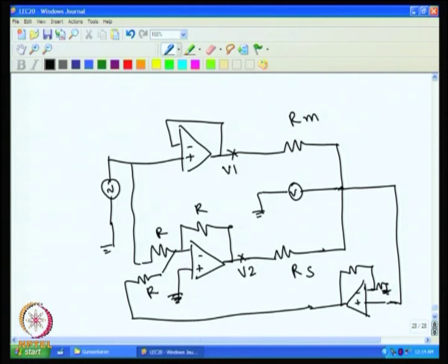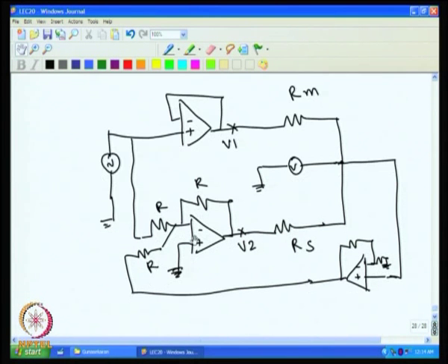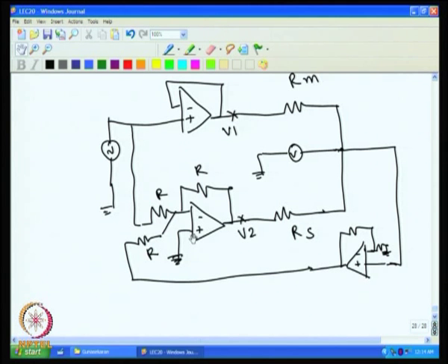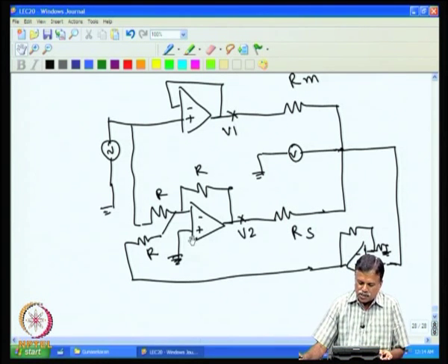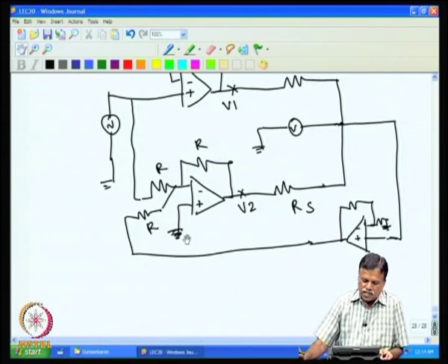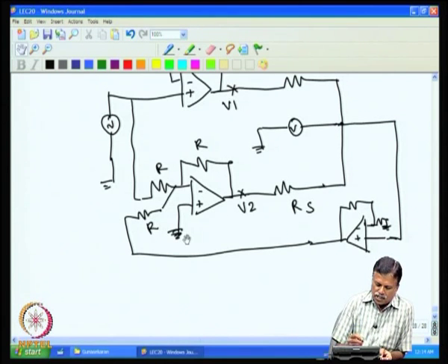All that one needs to do is measure V1 and V2 now with the voltmeter, or I can convert V1 and V2 into DC and make accurate measurements. In that case, it will give the correct reading, but there is no way that we can avoid voltage measurement, similar to what we had done in the ratio transformer bridge. So, essentially this bridge automatically balances.